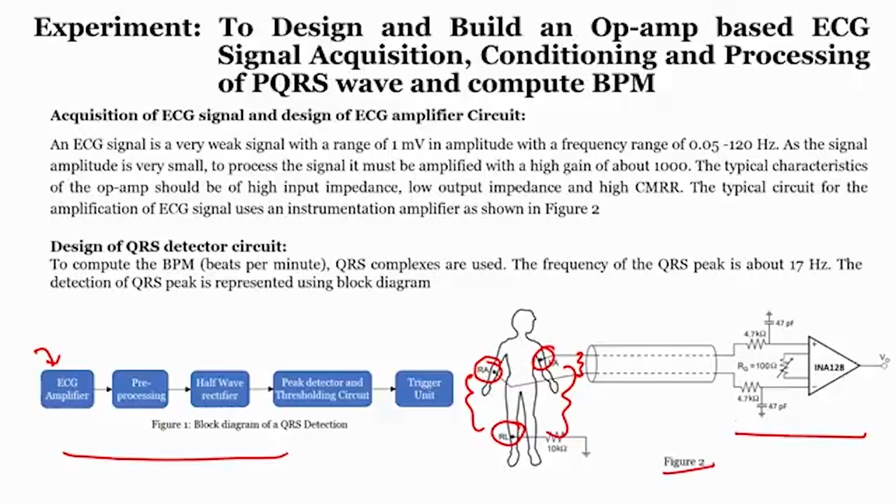Moreover, the other advantage is that instrumentation amplifiers can be used to provide higher gains to the system. Since the amplitude of the ECG signals is very small, we require a proper amplification stage too. So the required gain can be set by using our instrumentation amplifier. So in the ECG amplifier stage, we will be using an instrumentation amplifier because of these advantages.